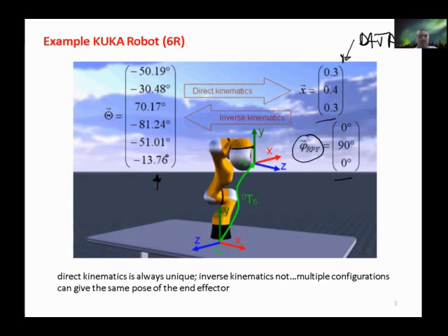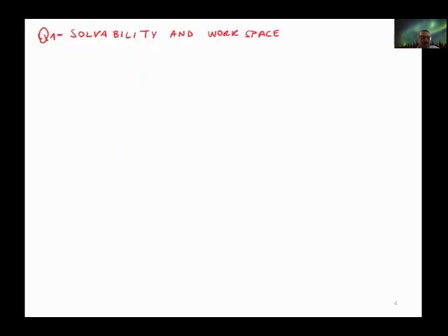We have multiple configurations corresponding to the same pose. We need to deal with this in the code. So in our inverse kinematics code, we need to consider options with if-then-else constructs in order to get one solution or the other. This is the same as we did for Euler angles, where we saw there are 2 solutions. In this case, the solutions will not differ from each other by a plus or a minus, but can be very different.